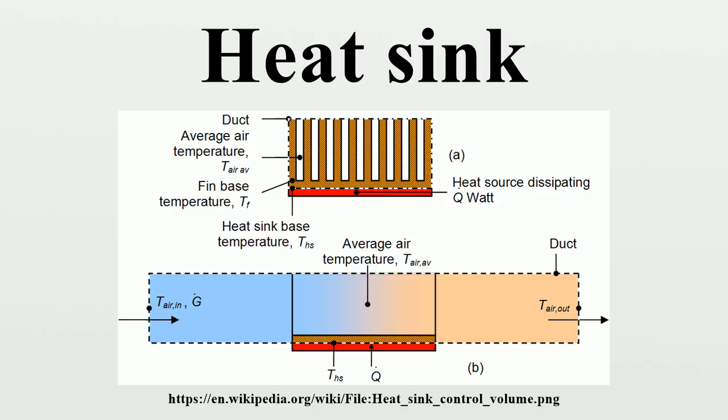Forgan et al. have published data on tests conducted on pin-fin, straight-fin and flared-fin heatsinks. They found that for low approach air velocity, typically around 1 meter per second, the thermal performance is at least 20% better than straight-fin heatsinks. Lasance and Eggink also found that for the bypass configurations that they tested, the flared heatsink performed better than the other heatsinks tested.